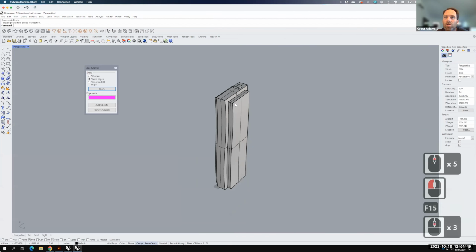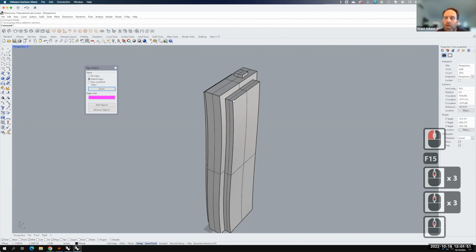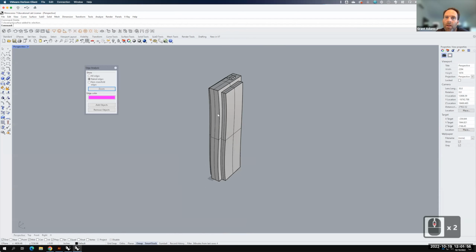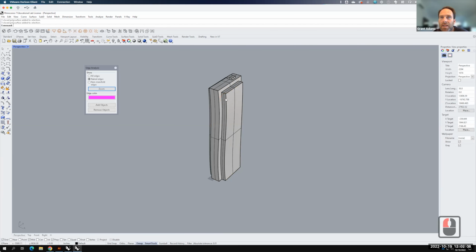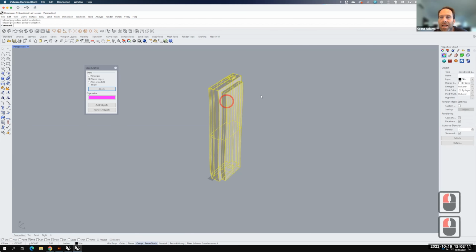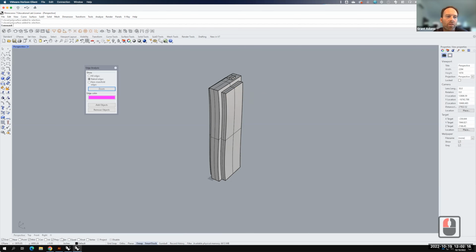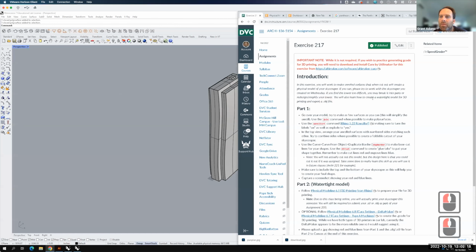Okay, so I now have those ready to work. The next piece of this is that I need to start doing 2 things. One, this is a NURBS model, so it's designed in Rhino. It's all mathematically driven. 3D printers work from polygonal models, kind of like SketchUp. So this object is going to have to be converted from its current state into a mesh in order to do it. By the way, I should have pointed out along the way that if you get a little bit lost, there is a tutorial here about how to get a 3D print ready file.